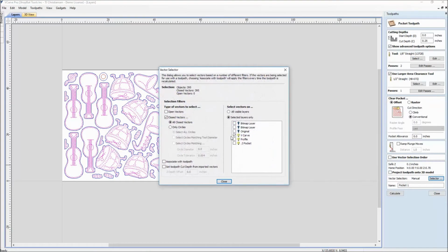And I would like everything not on the vcarve this time, but on the 0.3 pocket. And this is why it's a good idea to have named things, because here I start talking with the tutorial and moving along, and see, for this project to be proper, that has to have a 0.3 depth. So I know, oh shoot, my cut depth. So naming your layers helps with organization as well this way.